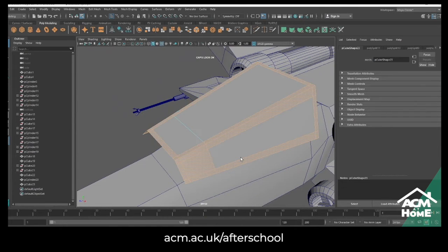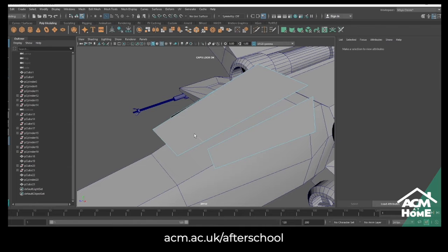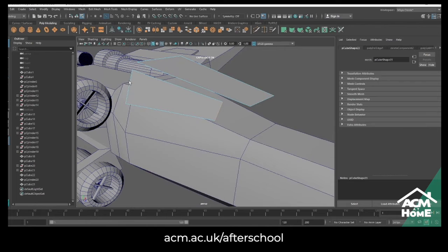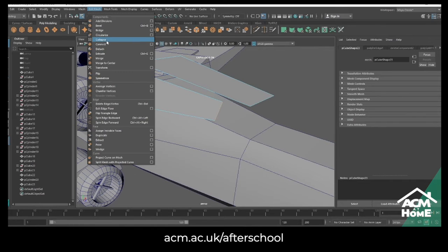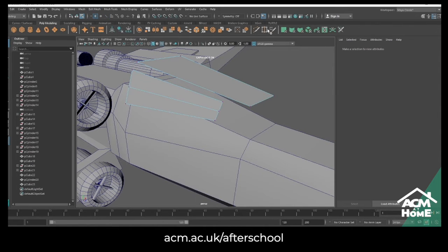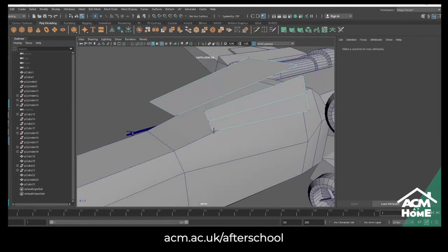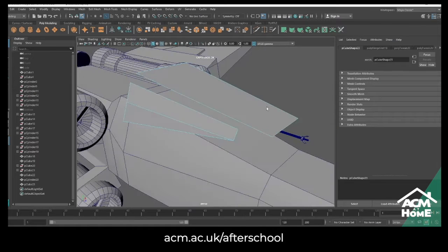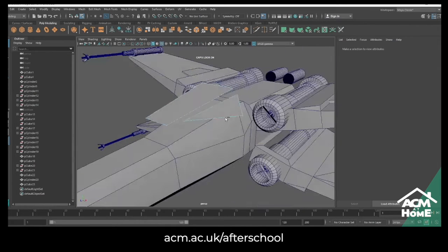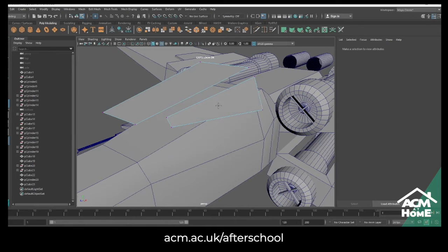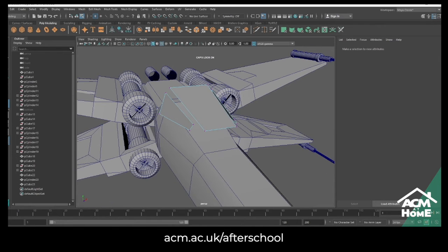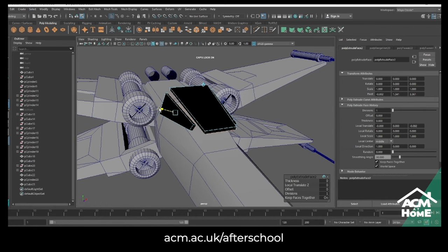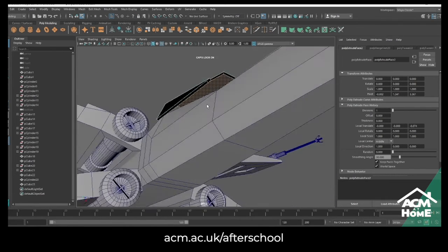With that part cut out or defined, I essentially delete the parts I don't need and get rid of the original one, and make sure that this has a little bit of a tilt to it. So add one edge to the middle and start welding so that there's a more unique shape. At first I tried to remove the edges that way, but I didn't like that. It took away too much. Once the shape was defined, I did an extrusion inwards,